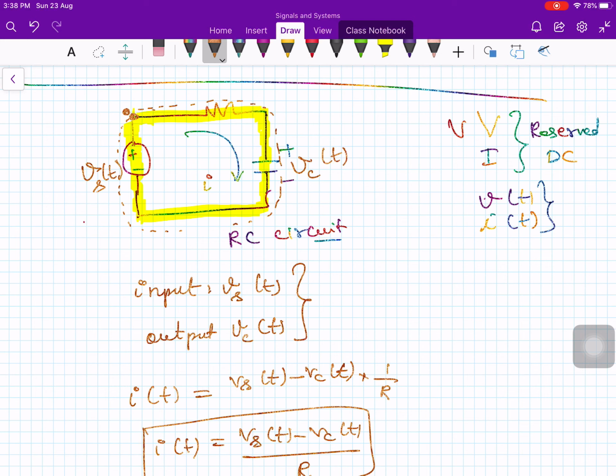When the current enters, that entering point is positive. It develops voltage with a positive polarity. And when the current leaves, that is negative polarity. Similarly, here also the current enters, so positive, and leaves, that is negative. So when you come to this point, then again you are looking at positive polarity. Whenever you see a device, find the polarity of that device. And again come here. If you are coming here, then again you are looking at a source, and the source with a negative polarity.